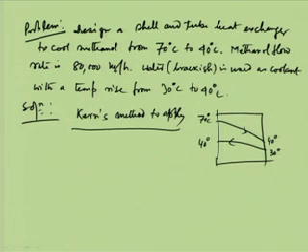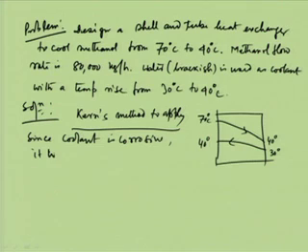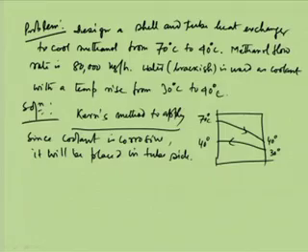For this design, since coolant is corrosive, it will be placed in tube side. We know that corrosive fluid we should place in the tube side. The reason is the corrosive fluid will corrode only the tubes, otherwise if we put it in the shell side it will corrode both the shell as well as tube surfaces.